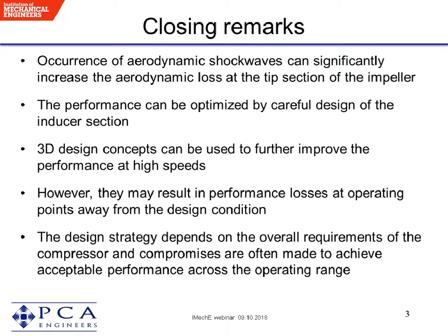My experience is that the range of stages is mainly affected by the Mach number. So if you want a wider range, you have to design for a lower Mach number. Of course, then you have no pressure rise, so it's a bit of an awkward thing. Essentially, what I'm saying is if you want a wider range, a two-stage machine, both of which stages are at lower Mach numbers, would have a wider range. Hamid?